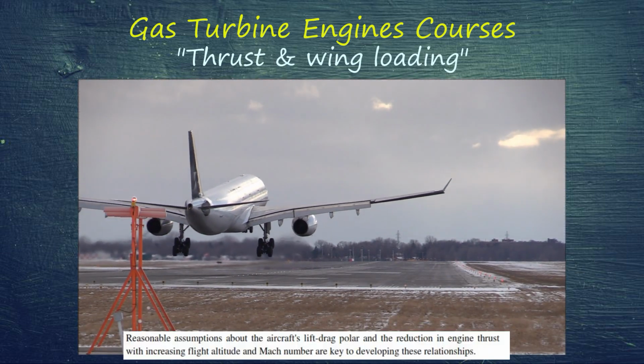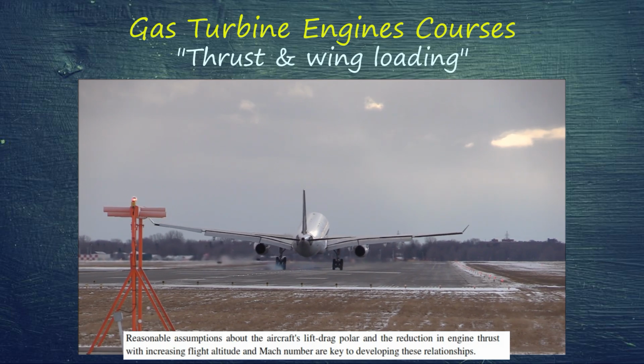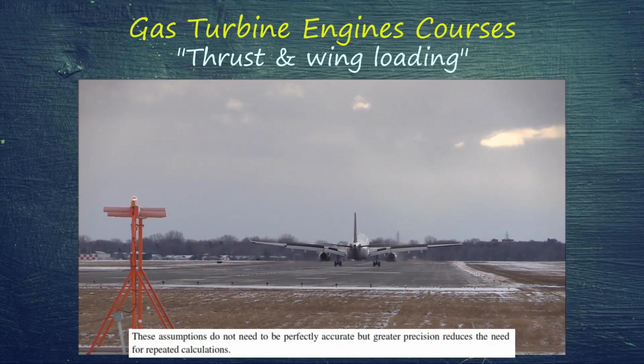Reasonable assumptions about the aircraft lift-drag polar and the reduction in engine thrust with increasing altitude and Mach number are the key to developing these relationships. These assumptions do not need to be perfectly accurate, but greater precision reduces the need for repeated calculations.